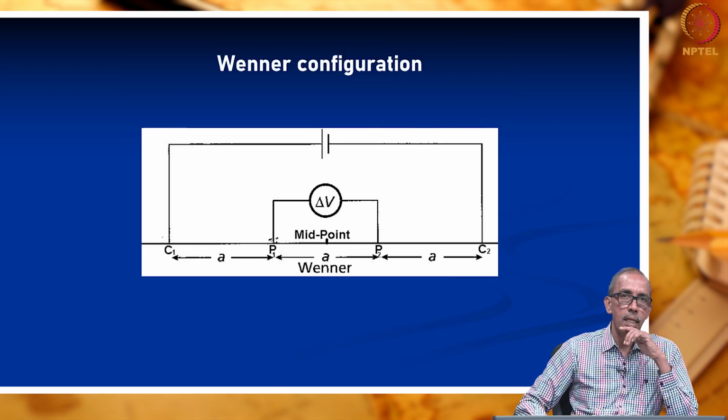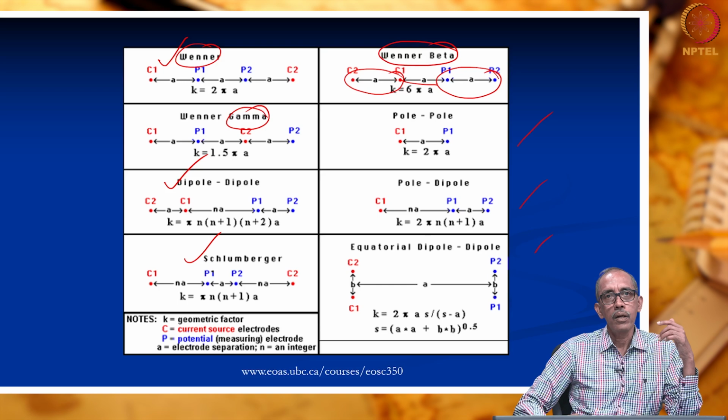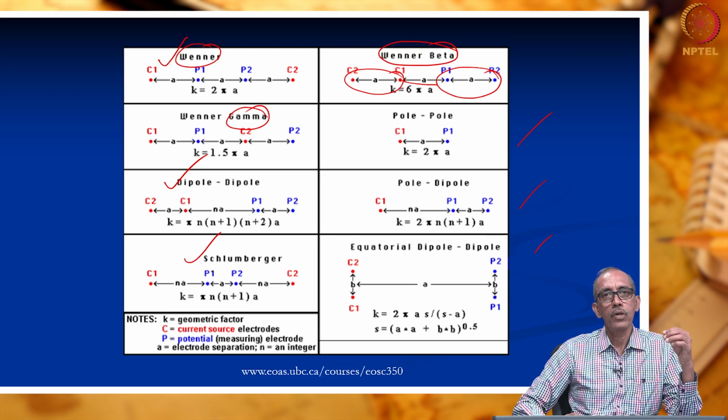Thus, during this lecture, we had a look into some of the factors that control the electrical resistivity. Especially, we had a look into how electrical resistivity measurements help us to understand about the aquifer parameters. The most important aquifer parameters are hydraulic conductivity and transmissivity. Then we had a look into how resistivity investigation is carried out on the land surface.